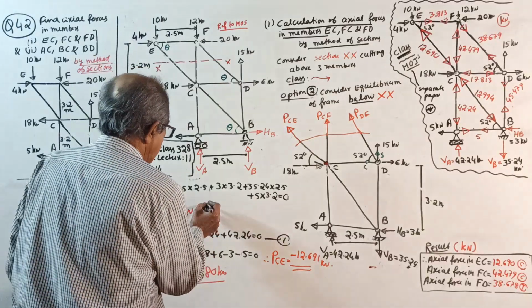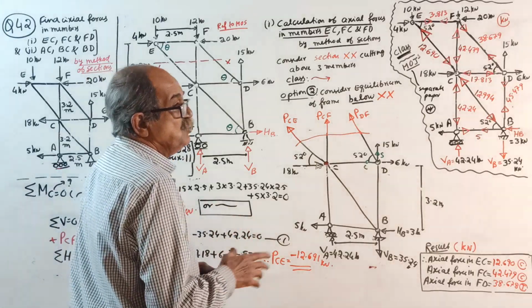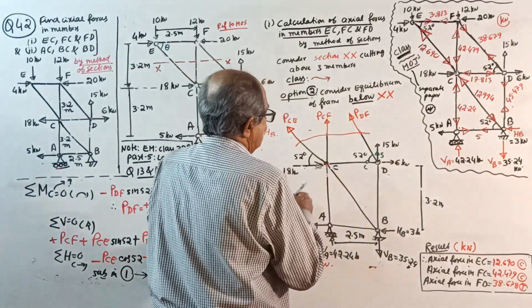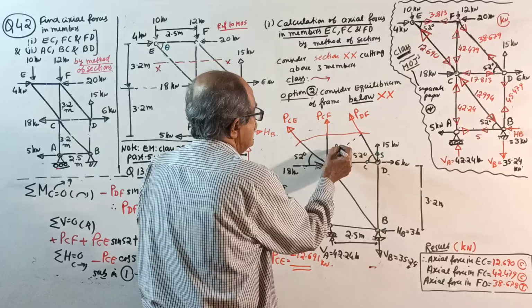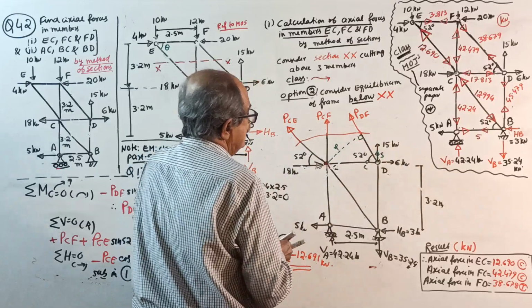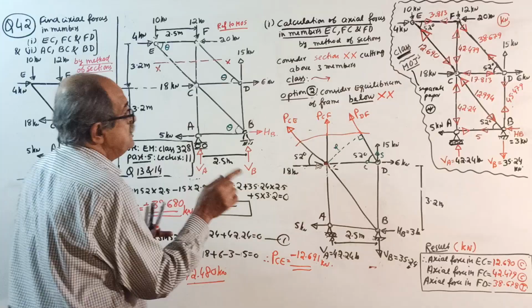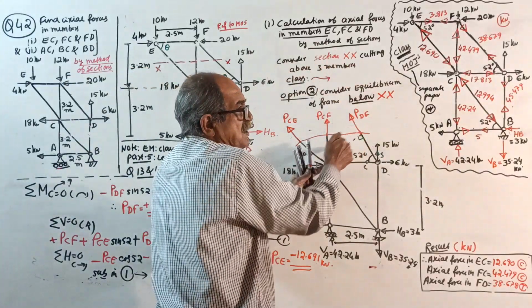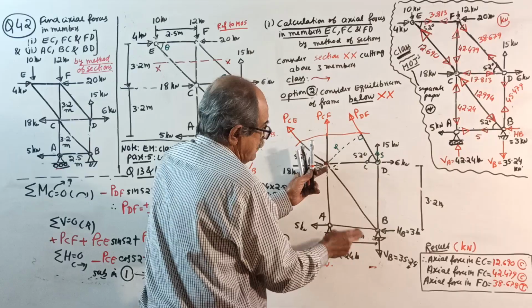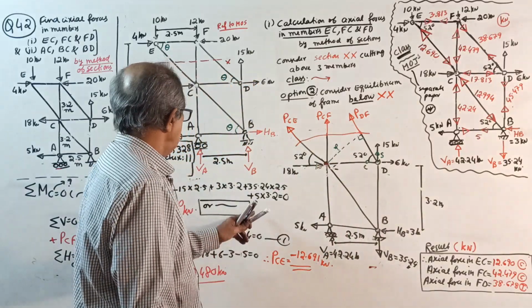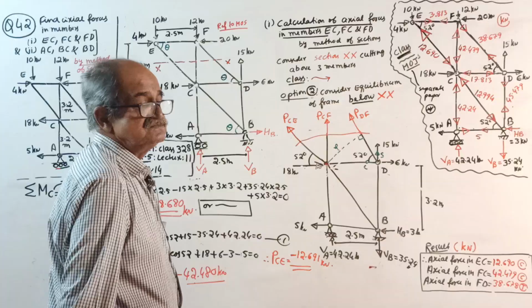See here, or make a note here. I will dictate now. You should write what all I am telling. If you do not want to resolve that force, you draw a perpendicular, not a big issue. Draw a perpendicular here, H. See, this is perpendicular. Then, instead of this sin and so on, this term will change over to minus PDF into H. How to get H? Sin 52 equals H divided by 2.5. So get the value of H, substitute. This term will change, others will come the same, 100% same answer.